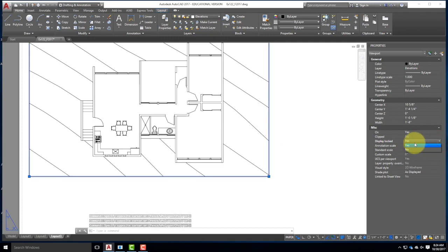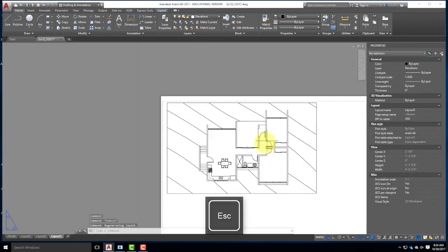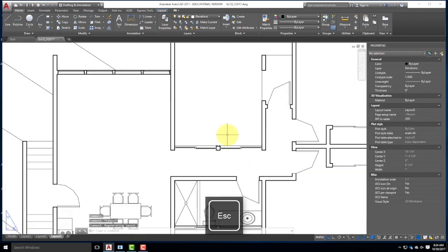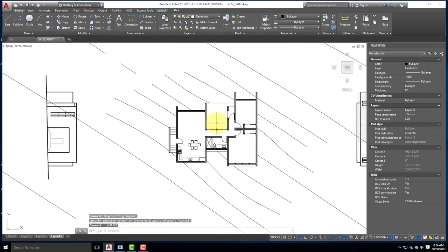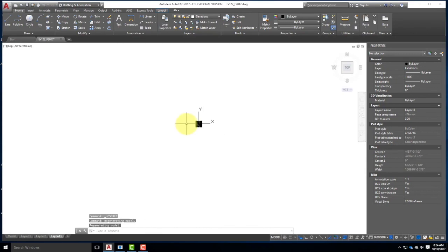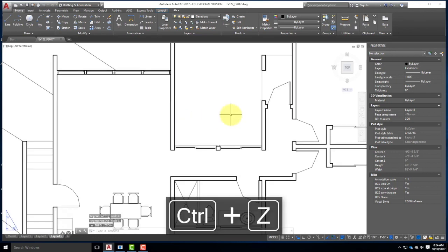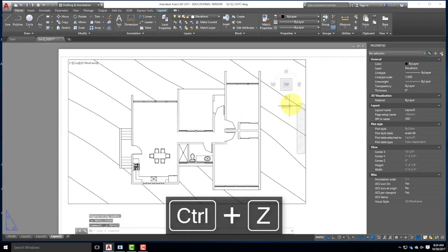And this is far worse than the last scenario: you're working and looking at something in your drawing, and you accidentally double click. I'm inside the viewport now. Wait, where'd my Paperspace go? Right? You can get locked inside a viewport. So just get in the habit, in which case undoing is the best strategy there.